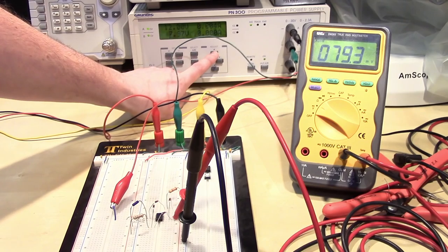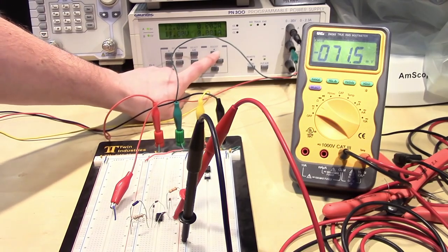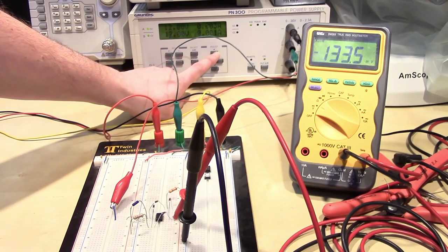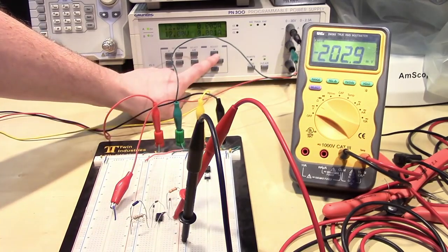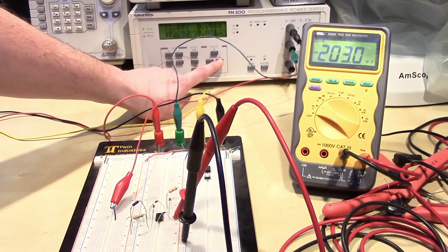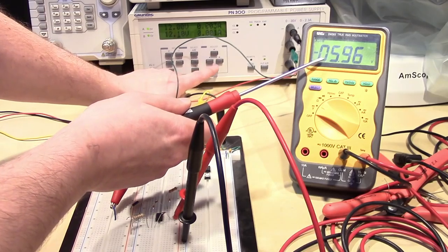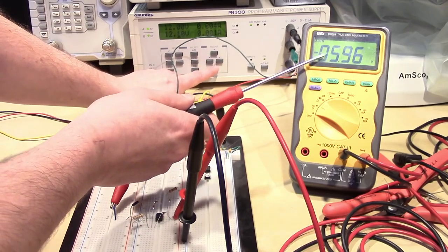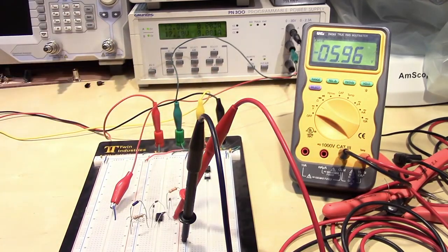So we're currently inside the window, so you can see that we're staying right around 0 volts here as I increase the voltage. And I'll go up here. I'm at 11 volts currently, so we're still inside that window. 12 volts. Output is still pretty low, just right around 0 volts, so it still says we're inside the window. If I go up to 12.1 volts, oh, there we've tripped it. So looks like about 12.1 volts is the high trip voltage here. You can see the output is being driven down to the negative voltage rail. So there you have it. It's a window comparator that detects 3 different voltage ranges with just a single op-amp.